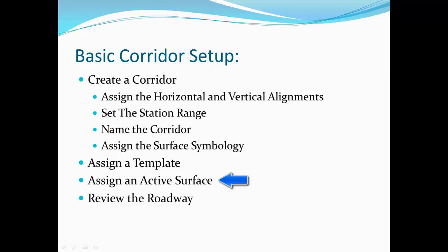However, if you have imported more than one surface into Corridor Modeler, or if you process a model, Roadway Designer will assign the last surface in the pick list as the active surface unless you set the lock option next to the active surface name. This is important as you add more surfaces for intersections and other existing and proposed surfaces that you may want Corridor Modeler to use for target aliasing.